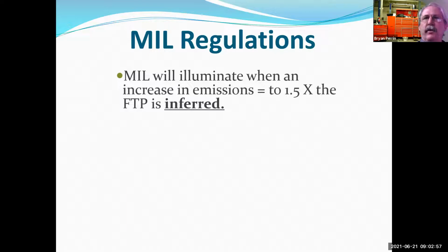So they put a vehicle in a room, run it through a specific set of operating conditions, and measure the total emissions produced by the vehicle in the room, not just out the tailpipe, total emissions. And they have to meet the federal test procedure for that year in vehicle classification. They have to put out less emissions than that. And to give you an idea how tight that is, if it takes a car a second longer to start than it's supposed to take, the vehicle will fail. I mean, they are very, very tight now.